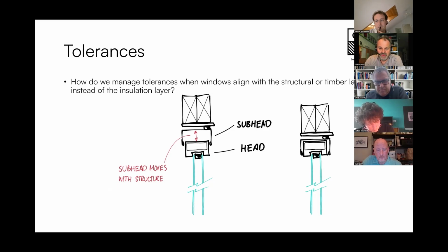So let's assume the structural engineer advises to have 20 millimeter movements acceptable within the facade top point. Then you can't just push it a little bit in because the tolerances from the building itself are not there, and you reduce it to 5 millimeter. Then in case of a load and the ceiling bends downwards, you have cracks in your windows because it's not capable of what you're asked for.